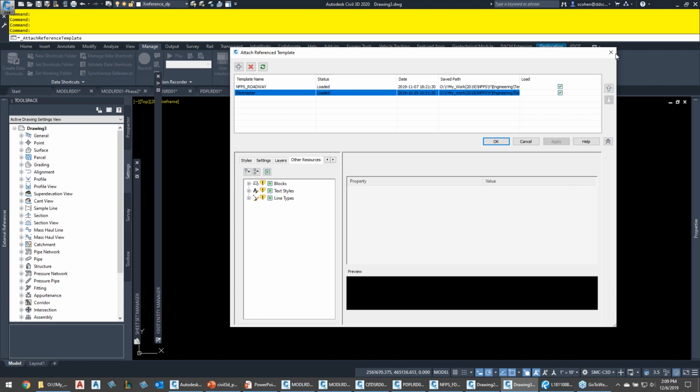Again, really great functionality. It's not hard to set up. So again, you just create a brand new file that's totally blank, and then you attach the reference templates from the location you want. And then when you do File New, you pick that blank file that's pointing to the reference template. Okay.